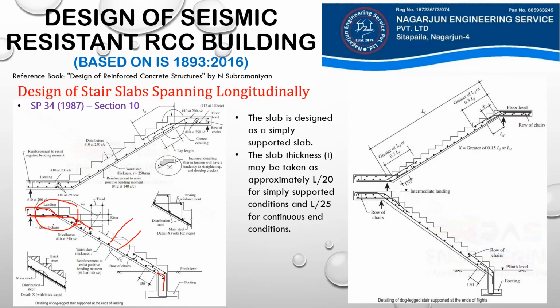And this scissor type arrangement is because at the junction of this mid landing slab and our inclined stair slab, negative moments may arise, and to resist those negative moments we have to detail in this way. This is one of the most important parts of detailing in the case of a staircase. Similar is the detailing from our mid landing slab to our top landing.